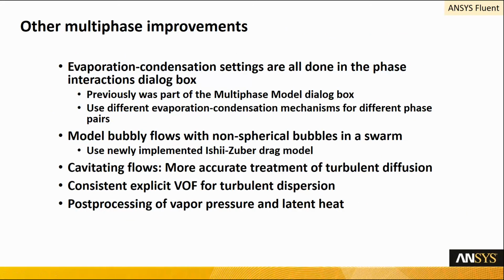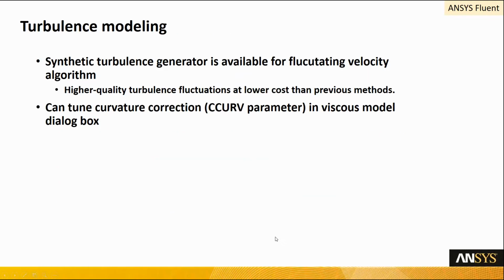There have been other multiphase improvements, particularly around usability, moving the evaporation condensation setup into the phase interaction box where it belongs, being able to use a new drag law here, the Ishii-Zuber model, which CFX users find really beneficial, and some improved numerical treatments in cavitating flow and VOF, and some new output variables for post-processing.